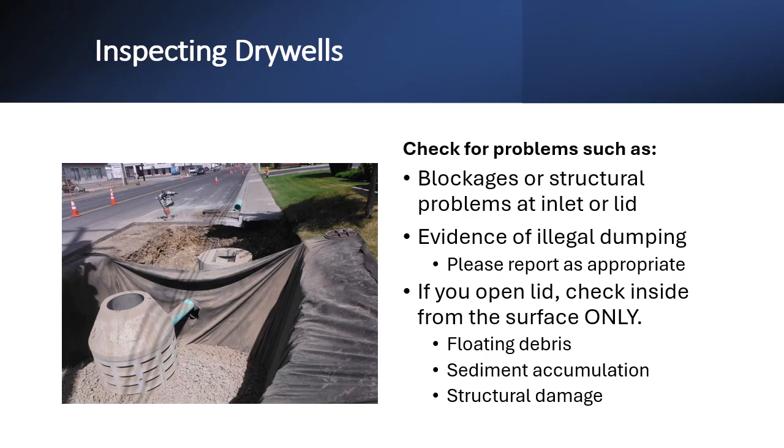Note that drywell lids can be very heavy. They could be difficult to put back into place properly or retrieved if dropped into the structure. If you do open the inlet or lid, please do so only with the proper equipment and protective gear. Inspect the inside of the drywell from the surface only. Do not climb down into the drywell, and be cautious about slip-trip hazards around the open drywell. If you believe there is a subsurface problem, hire a contractor to inspect the inside of the drywell.